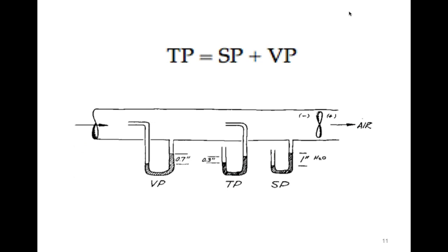Okay, so now the tube furthest to the right could be a simple plastic tube. Now, if that fan is not running, the pressure on the side of that tube, which is open to the side of the duct, is 14.7 pounds, the same static pressure that's going on all over the world. On the other side, it's also 14.7 pounds.